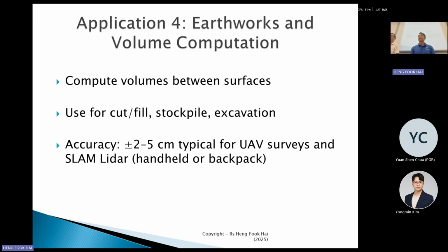So what they do is they stack up sand, right? So when you stack up sand, in this type of application you come in with some LiDAR scanning, you're able to capture this sand and calculate the whole volume, and you're able to convert the density of the sand and you will know the weight of the sand.